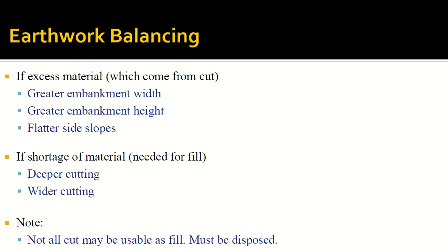Okay, and you can have two cases. You did more cut and less fill. So now you have excess material on the site. You have extra material on the site. Okay. Now the option is, okay, I have this extra material, I'll bring the truck and I will get it disposed of somewhere else. Okay, and it will take cost and you may have to take permission as well. Because you cannot just throw material anywhere, right? Okay, there are areas where you will throw it and so on. Or you can do one of these things.